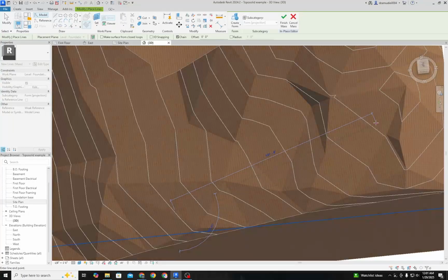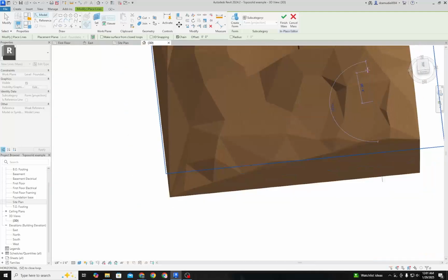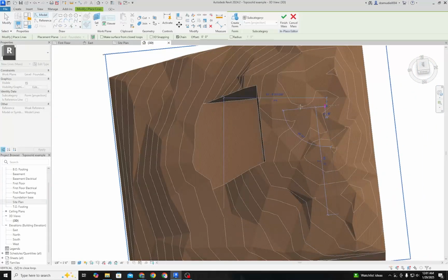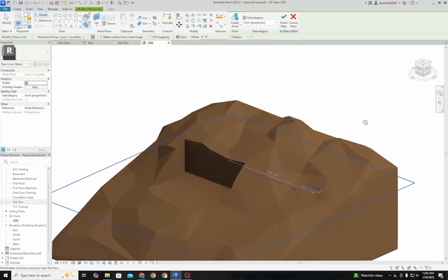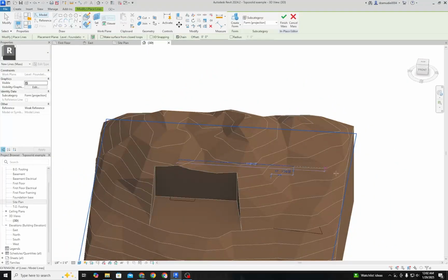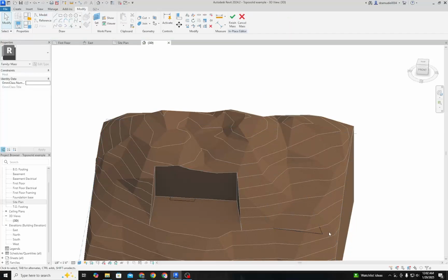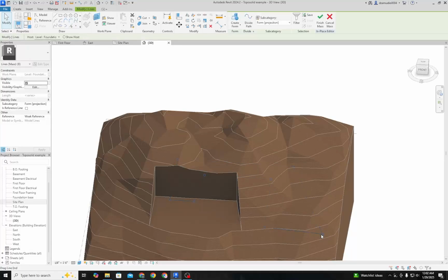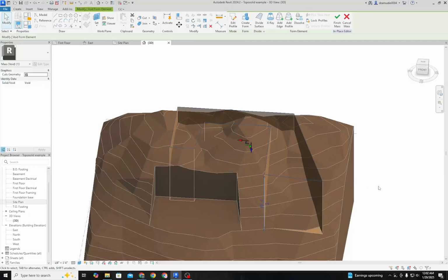So we'll move our camera view to get a better understanding of our layout, just because it's a top-down layout. We'll intersect that void form that we have earlier, and that obviously won't cause any issues, but it will allow us to get a clean cut. And then once again, we make sure that we deselect everything, and then we select all the lines from that floor plan or that layout, and then we'll do the same thing. Void form.